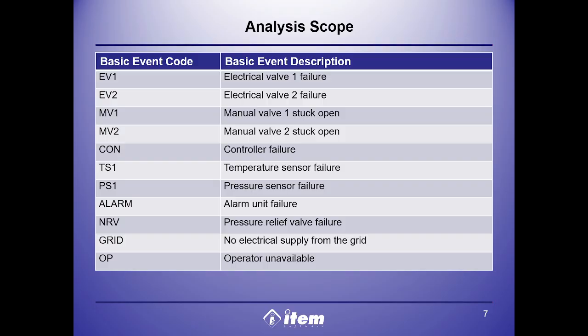Now that we understand the general procedure, let's apply those first crucial steps to our reactor vessel. On this final slide, we are defining the exact scope, resolution, and ground rules for the models we are about to build. For our analysis scope, we are focusing strictly on the failure of our safeguards during a runaway reaction. This means we are including the automated sensors, the electronic and manual valves, the operator, and the mechanical relief valve, while excluding the primary cooling loop itself. For our resolution, we will model down to the major component level.